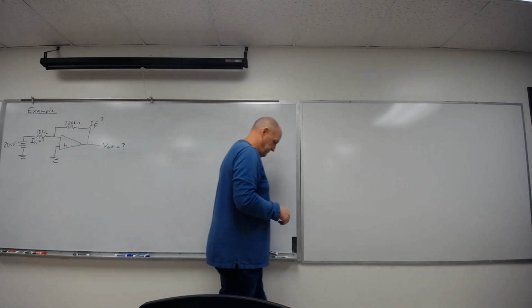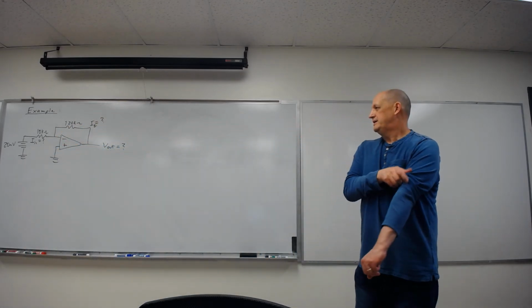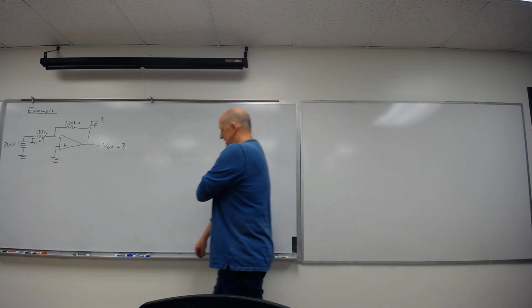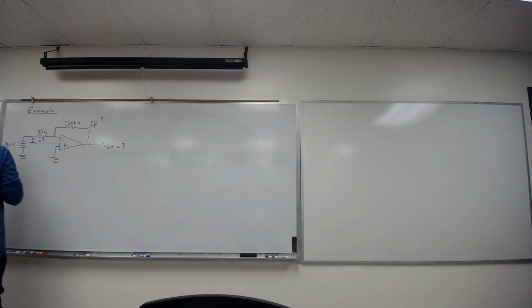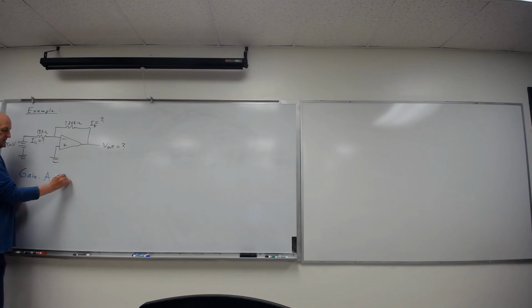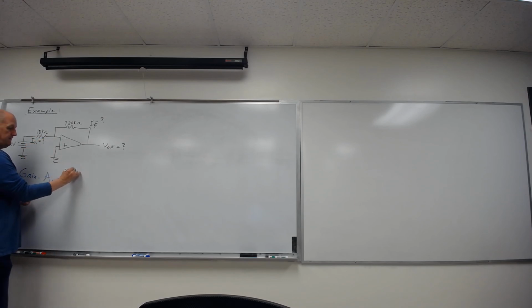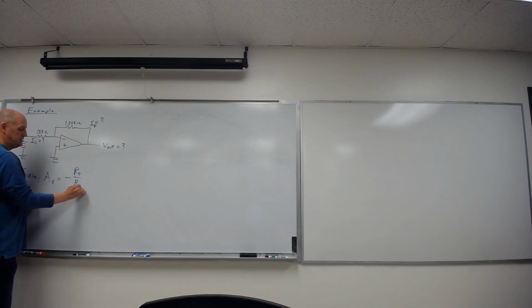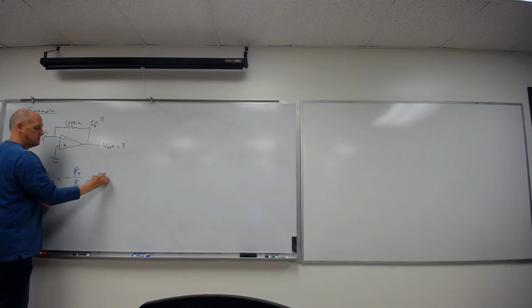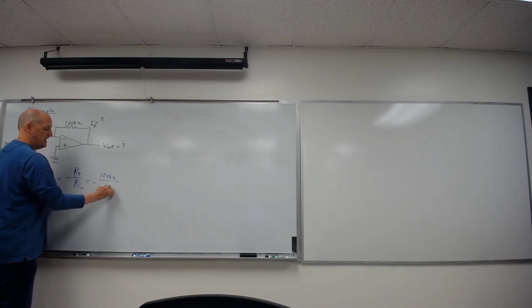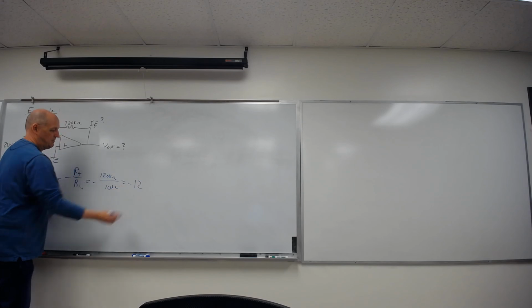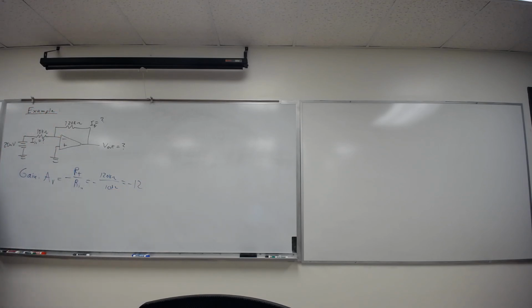Start by getting your A for your gain. Yeah, I can find my gain. What's my gain? Resistor 2 divided by resistor 1 plus 1. Right, gain by definition, so we found this, it's an inverting op amp, so I need a negative. It's the feedback resistor over the input resistor. Feedback is 120 kiloohms, input is 10 kiloohms. So my gain will be minus 12. Is it the non-inverting one that you add 1 to? Yes. Okay.